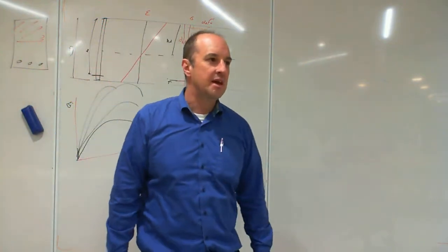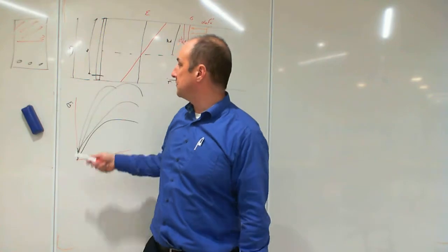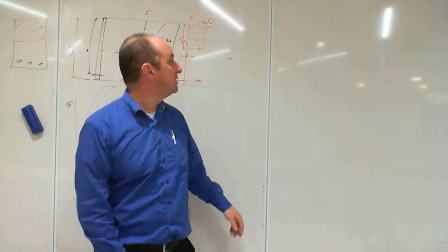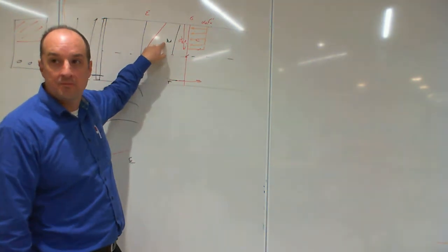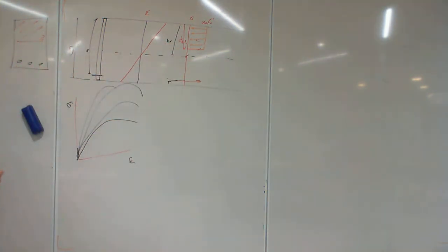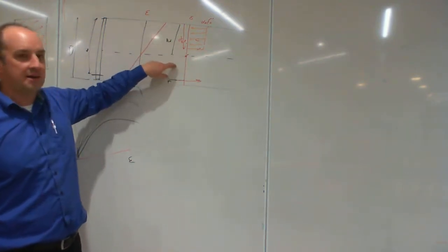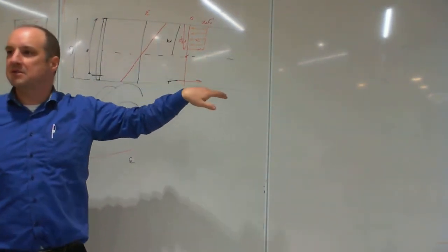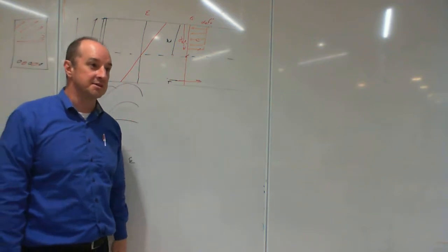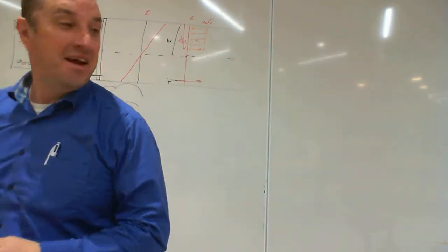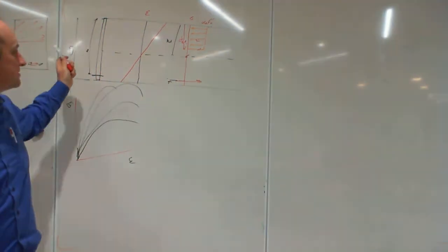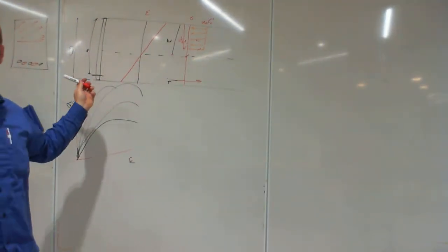If you under-reinforce the beam, so if this area of steel is quite small, the neutral axis is going to be quite high, Ku is going to be a very small number. If you over-reinforce the beam, you pile in a whole bunch of extra steel here, Ku is going to be quite large, and the beam fails in a brittle manner. Everybody dies. No one likes that. All right. Now, so that's the singly reinforced concrete beams. That's what you cover in that topic.